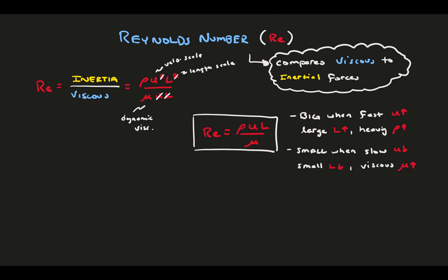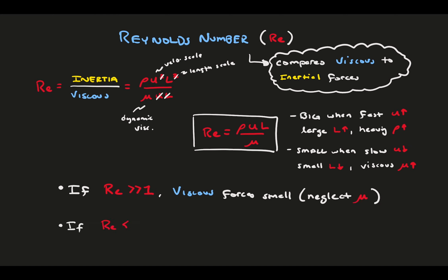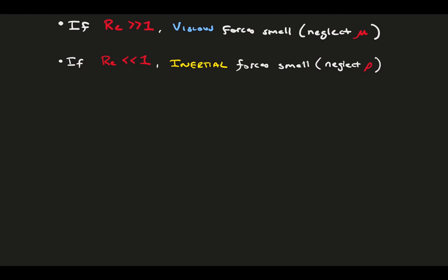Using the Reynolds number, we know what fluid force sources we can neglect when considering our flow. For example, when the Reynolds number is very large, we can ignore the viscous forces, meaning viscosity goes to 0. When the Reynolds number is very small, we can ignore the inertial forces, which is like neglecting the density. We use the Reynolds number to tell us which equations we need to use to find the forces on our vehicle, because these assumptions change the equations.